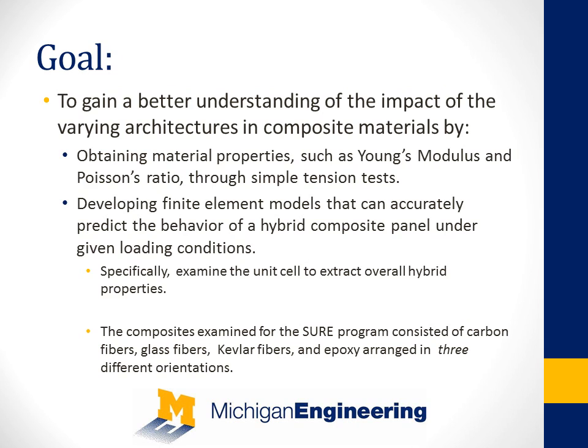The goal of my summer research was to get a better understanding of the impact of the varying architectures in composite materials. I wanted to obtain Young's modulus as well as Poisson's ratio through experimental tension tests as well as computational tests. The composites that I looked at for the SURE program consisted of carbon fibers, glass fibers, Kevlar fibers, and epoxy arranged in 3 different orientations.